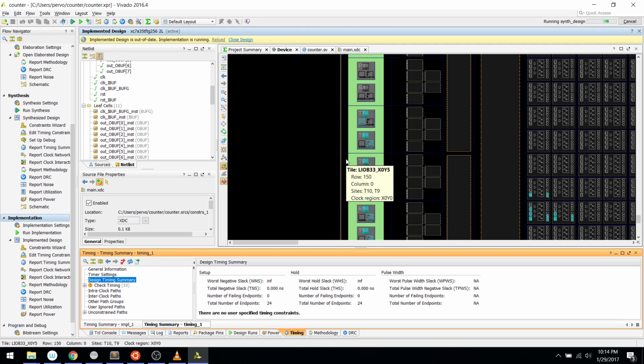By the way, when I'm doing my own RTL programming, I don't spend any time, if I can help it, inside this program. First off, a lot of these steps, as long as you're not doing anything involving graphical stuff, you can do from the command line. So all these tools are available from the command line, although you usually have to write some Tcl code in order to string them together, but that's fine. But even beyond that, the tools themselves, even in Tcl mode or command line mode, are not great. I do tend to use different workflows. It doesn't require me to run all these slow steps all the time, because as you can see, even for a trivial design like this, it really kills iteration time.